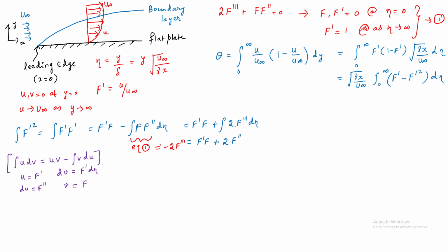Okay, so now let's substitute this here. We get x by u∞ times: if we integrate f', we get f, and we have to substitute the limits of integration, 0 to infinity, minus f' f from 0 to infinity, minus 2 f'' from 0 to infinity, right?